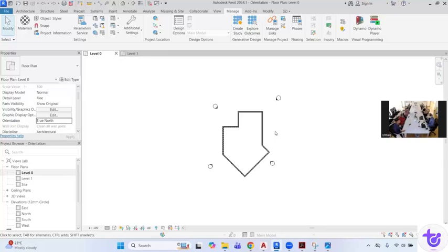If we create our model in a higher version and export it as IFC, it can be opened in a lower version also, no? Yes, you can link them, or vice versa. You can export an IFC and use it in the higher version, just in case you don't want to upgrade the Revit version for some reason.